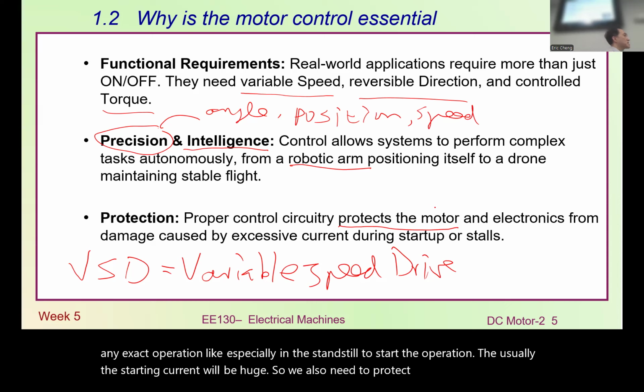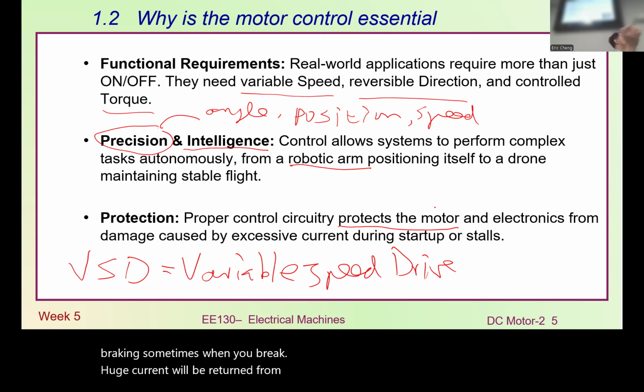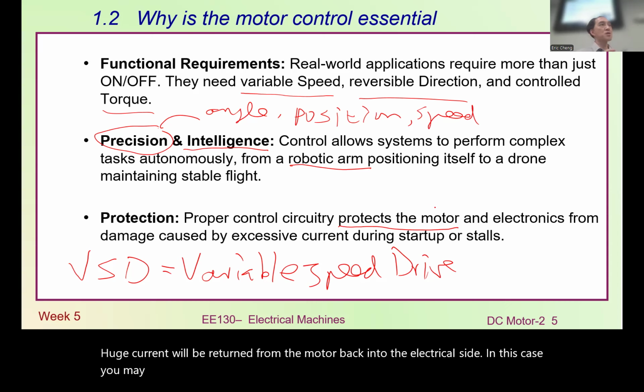And also for braking, sometimes when you brake, a huge current will be returned from the motor back to the electrical side. In this case, you may also need to make sure that there won't be excessive current to damage your power source.